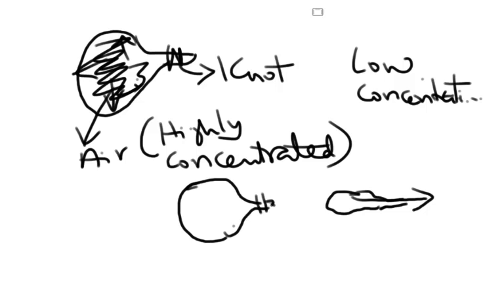Now, similarly, when the P and N materials come together, due to diffusion, holes from the P region, where they are in excess, get closer to the junction to move over to the N region as there is less concentration. The opposite happens in N-type material.